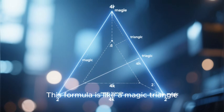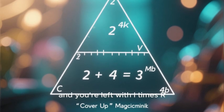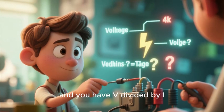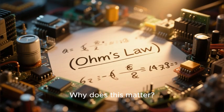This formula is like a magic triangle. If you know any two of the values, you can always find the third. Want to find the voltage? Cover up the V, and you're left with I times R. Need to find the resistance? Cover up the R, and you have V divided by I. It's incredibly powerful.